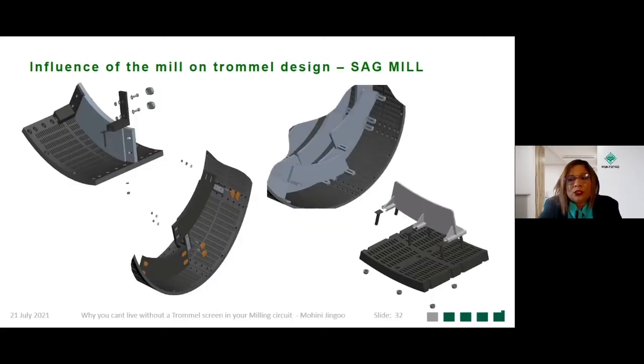The typical mountings that we use for the ball mill wear bars and scrolls do not apply to large SAG mills. When we look at SAG mills, we bolt the wear bar and the scrolls to the trommel frame. It's important to note that when we bolt steel to steel, the steel bushes in the pinning holes need to be removable for any flex.